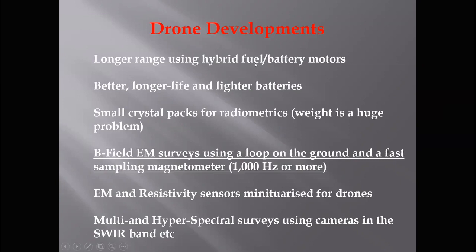So then your issue is, can we use a hybrid fuel? Can we use fuel? Or can we use a hybrid which is using fuel and batteries? Problem with that is we have even more issues with fuel because governments fear that when the drone crashes, the fuel is going to explode and you're going to start a fire. And if that's in an urban area, then you have massive problems. So we're looking rather at better, longer life and lighter batteries. And as we all know, that's happening all the time. We try cobalt, we try vanadium, we try lithium, and we just keep going.